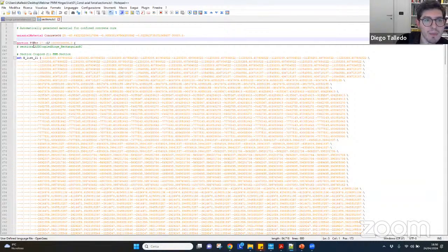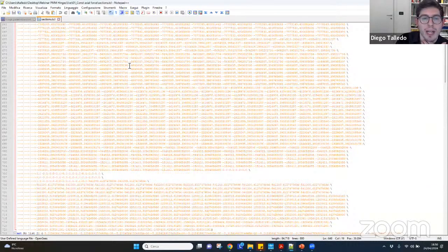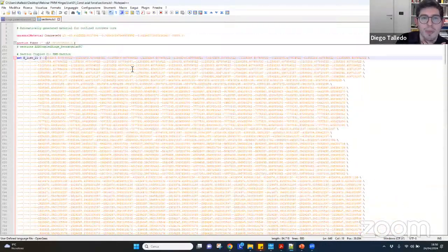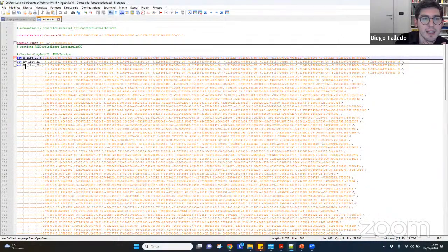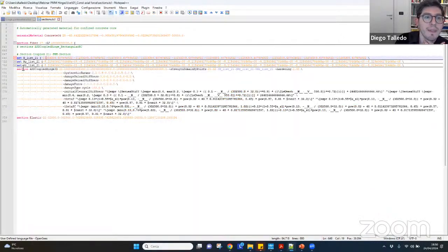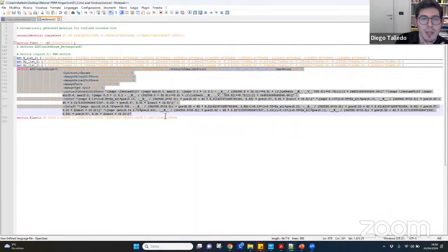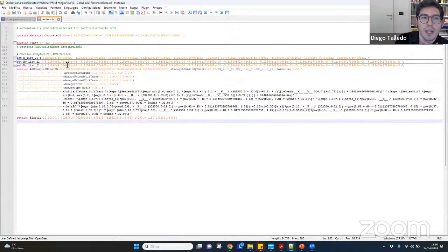Okay, and this is our fiber section. I close it. And then we have this structure domain that I mentioned before. So you see, it can be quite cumbersome to insert these values in OpenSees. So STKO has this big advantage that creates for us N list, MY list, and MZ list. And this is our OpenSees code for creating our section.